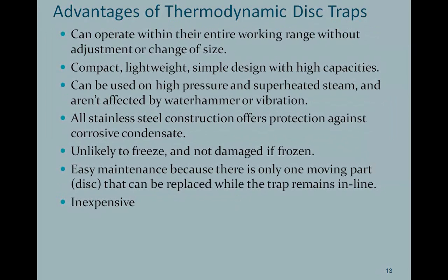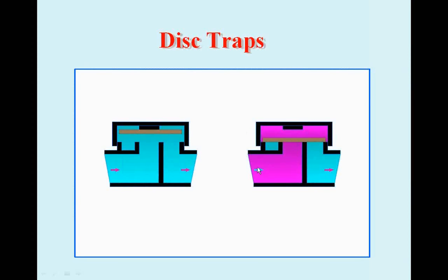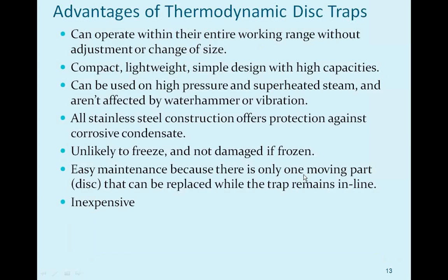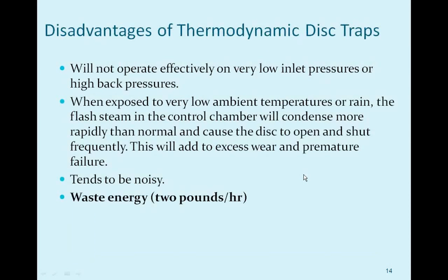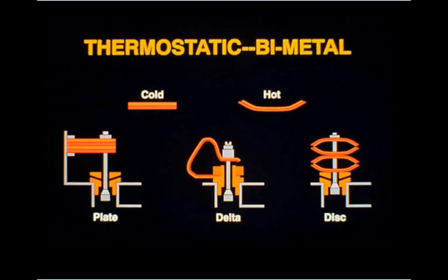Going back up to the picture, again, these need some steam to pass through here and pull the disc down to close. So same scenario, you're going to use about 2 pounds an hour, assuming they're working at peak efficiency.